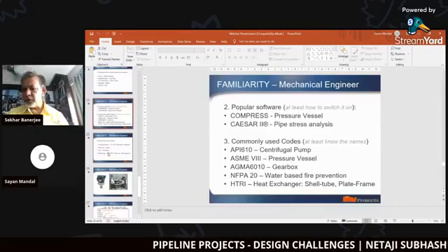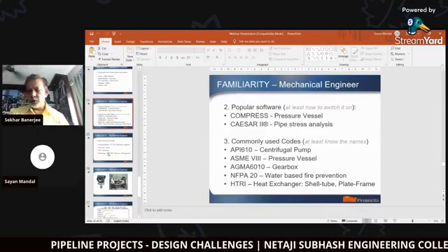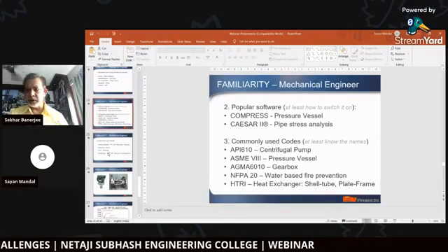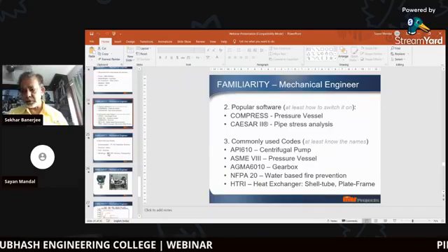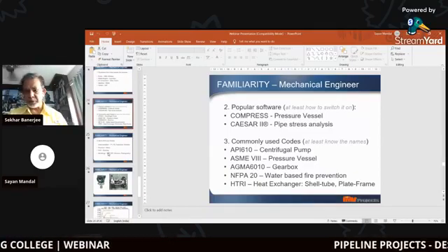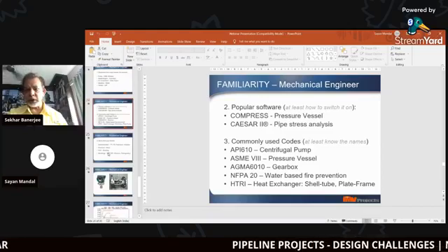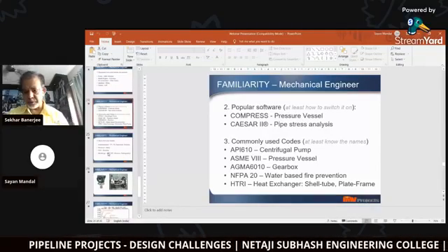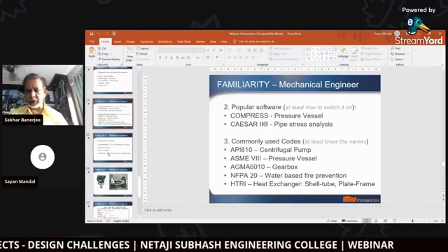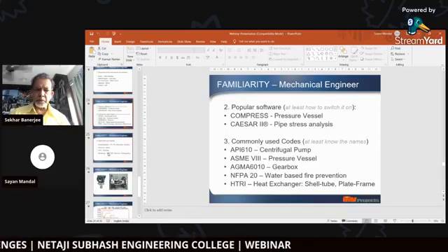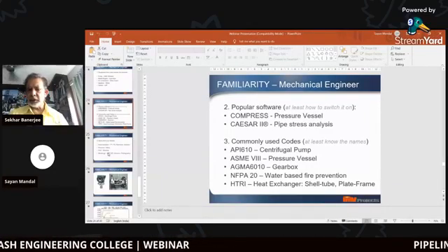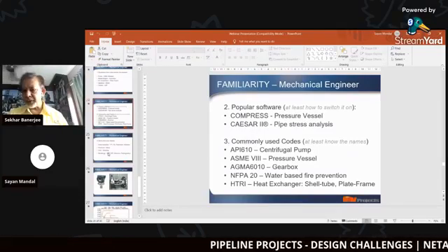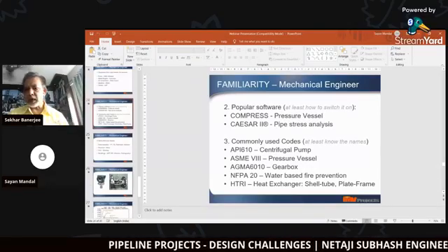So what type of pump do you require for all these things? You go to the market to buy a pump of your specification for drinking water and sanitation. Is it the same pump? No, probably not. For drinking water, you may need a stainless steel pump because there is a code for drinking water systems. For sanitation, you can probably use a cast steel pump, or maybe a cast iron pump will also work. If you are putting in an oil filling station, then you need a submersible pump, very small type, very industry specific, or an API 610 pump.